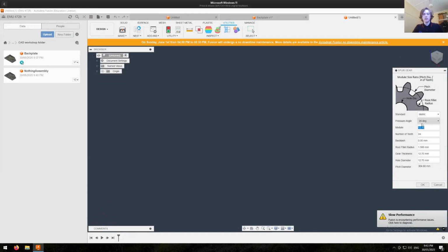Well, let's see. If I make this 20. Oh, that's not a number. I just put in gibberish. We put in 20. Oh, okay. So pitch diameter goes up a lot. So what if we make it small? What if we make it like 10? Well, it goes down. What if we make it like 5? Goes down. What if we make it 1? It's giving us a warning. So I'm going to leave it at 5. But it's still not small enough, because we need to get pitch diameter down to 70. And it's 120.